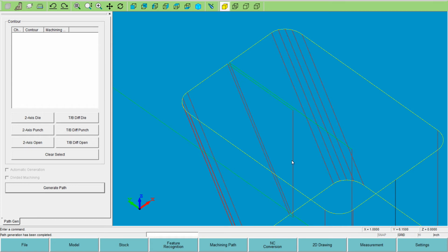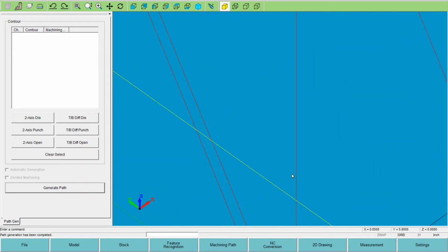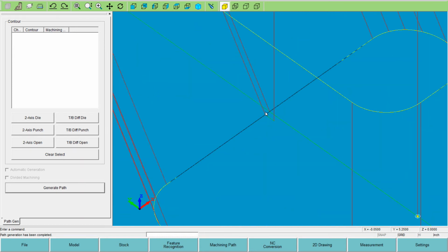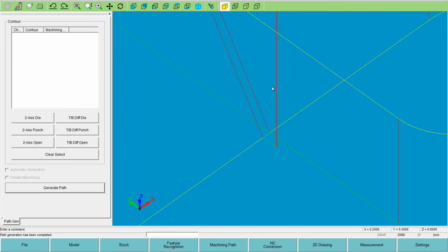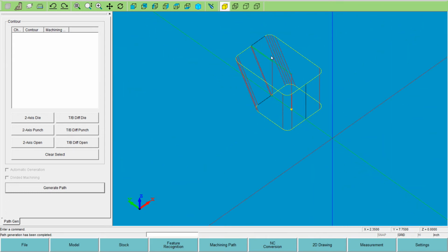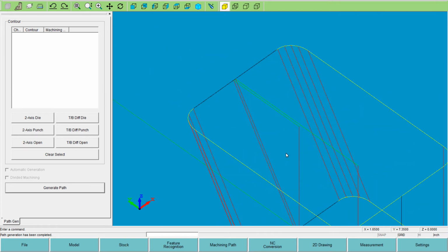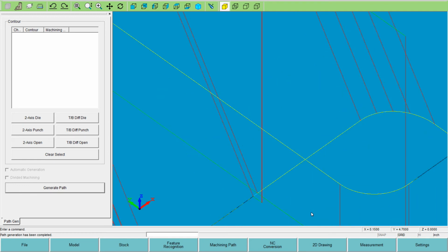Here was the little release move. See, look at how far on the top it has to move back. My reference plane was the bottom. And so it moved back that 100 thousandths in while the wire was straightening up. So it's doing a little 50 thou move on the bottom, and it's doing this, looks like about an inch long move on the top, but the reference was the bottom in this case when we did the feature recognition, right?